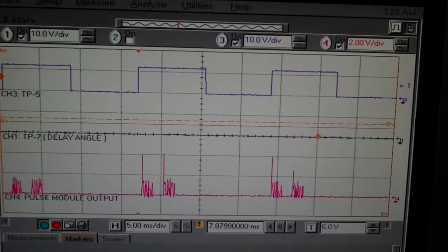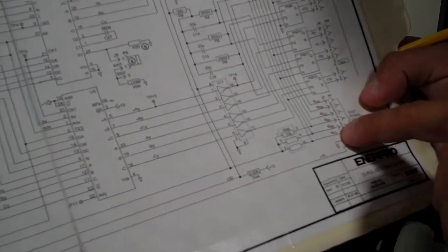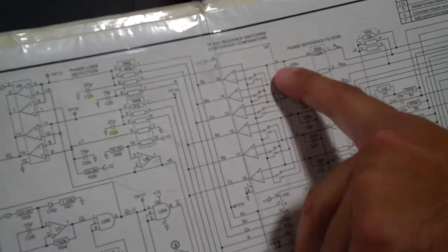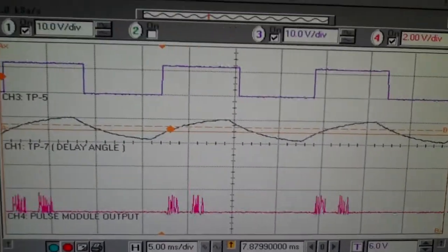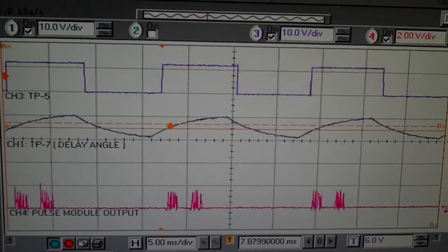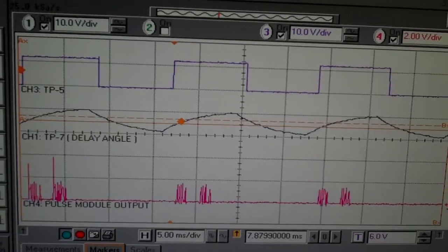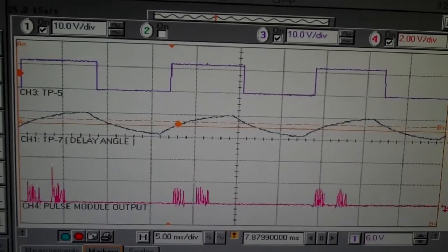With that information, we're going to walk the circuit. We just show what J7 has. Again, these signals can be square waveforms, or they can be sinusoidal waves, about 2 to 5 peak-to-peak volts coming in here. Now, the next stop is U5, position 2, and we're going to take a look at the effect of the RC filter on those references that we brought in at J7. So this is the RC filter.